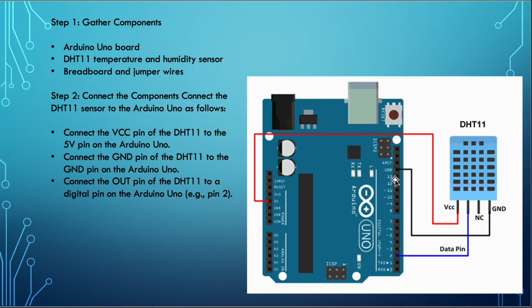Because this is using only 5 volts and we are not going to connect any other sensors or devices on top of this which consume more power, it could work from the USB port. The power from the USB port is more than enough. If we are to disconnect the USB port and just use this as a single device, we would need to supply electricity as well.